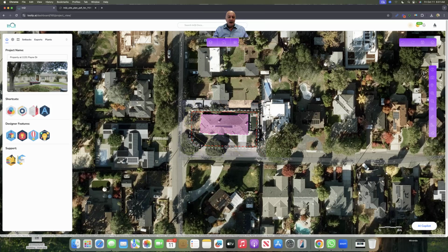Now, in this corner lot, what we want to do is create a couple of setbacks. Usually on the setbacks, you have from the side, because it's a corner lot, you have setback, and you can see the house is set back into the property. So let's go mark those, and then we're going to mark some utilities, and we're going to talk about some additional features. Now, you notice that there is an H line here on this paved road, and there is an E line, right? Let's put the 25, I think it's a 20 or 25. Let's go with 25: 25 off of E and then 25 off of H as a custom setback.